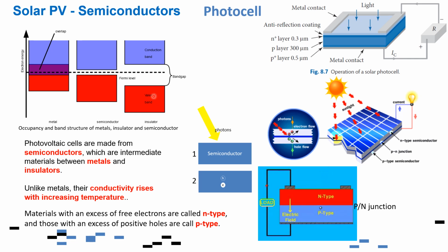But in their natural state, semiconductors are quite poor conductors, primarily because a current requires the flow of electrons, and semiconductors have the valence bands filled already. These are already filled with electrons, so they don't really allow the flow of electrons. In order for the conductivity to increase, we can increase the temperature, or we can change the material by doping the semiconductors.